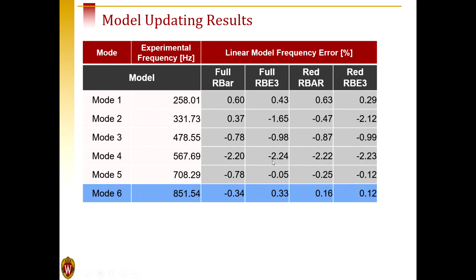We had also actually done a test on a single beam that was uncoupled from any others, and we knew that the Young's modulus we had was the right value for the structure, so we didn't want to go change it and mess that up. So basically our model's probably just missing the parameter that we need to get that mode to dial in.